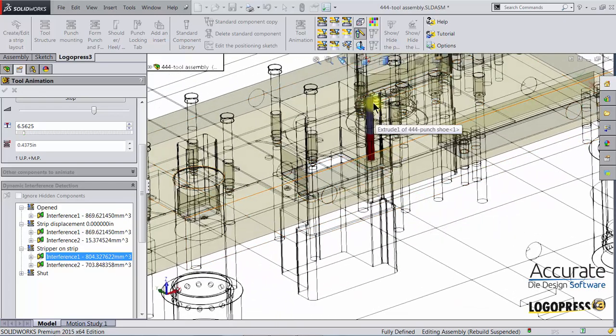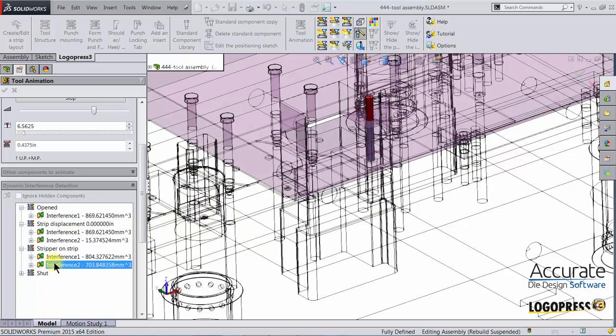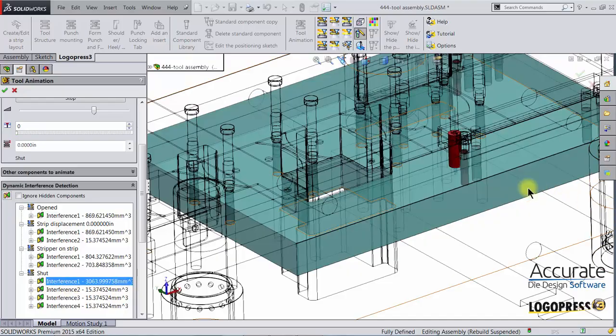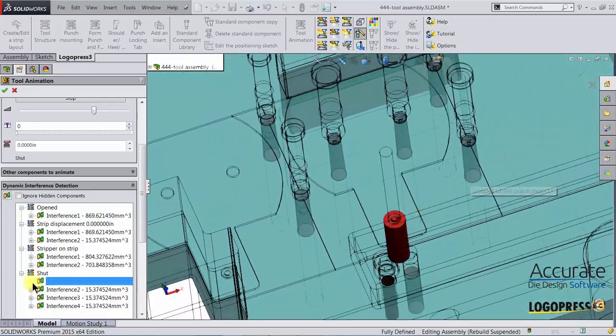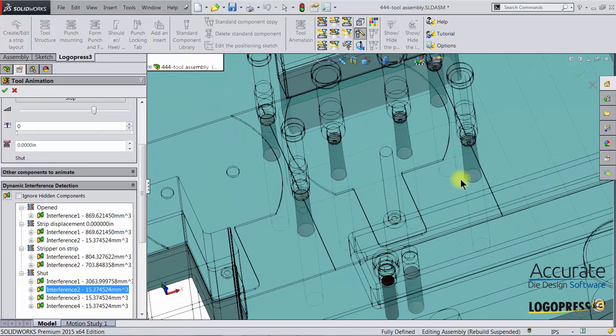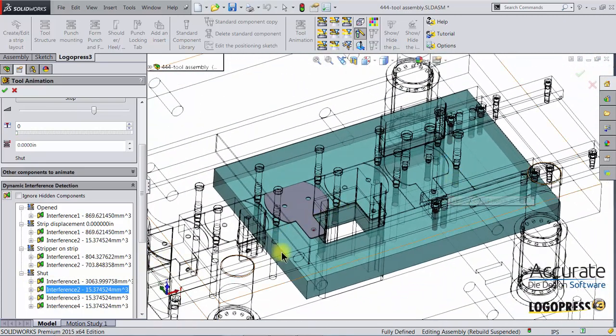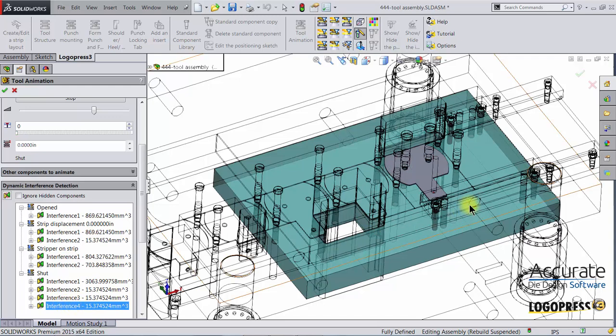We have not yet mounted our two dimple punches yet, so we'll just take note of those. Over here, same thing for our mounting of our dimple punches and die. Did not clear out for the dimple here in the die block. Same thing here and here. See, we just make notes of those interferences so that we can correct them, and then of course once that's